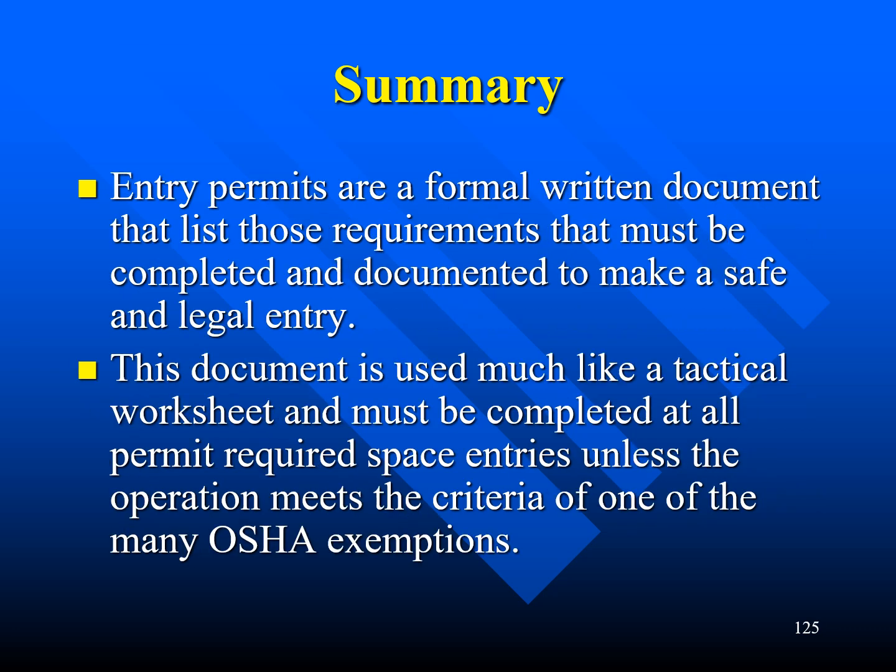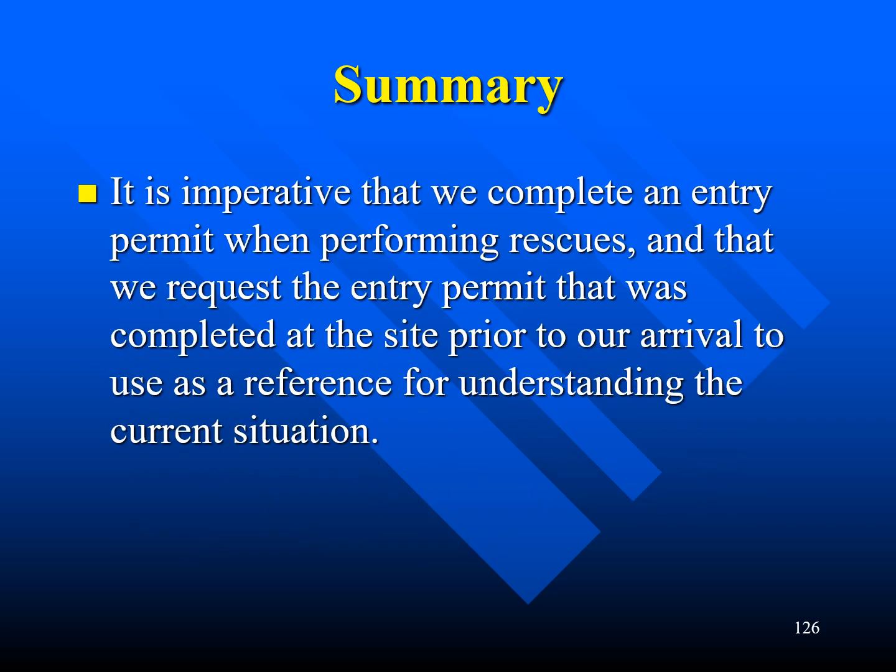Entry permits are a formal written document that lists those requirements that must be completed and documented to make a safe and legal entry. This document is used much like a tactical worksheet and must be completed at all permit required space entries unless the operation meets the criteria of one of the many OSHA exemptions that I just talked about. It is imperative that we complete an entry permit when performing rescues and that we request the entry permit that was completed at the site prior to our arrival to use as a reference for understanding the current situation.